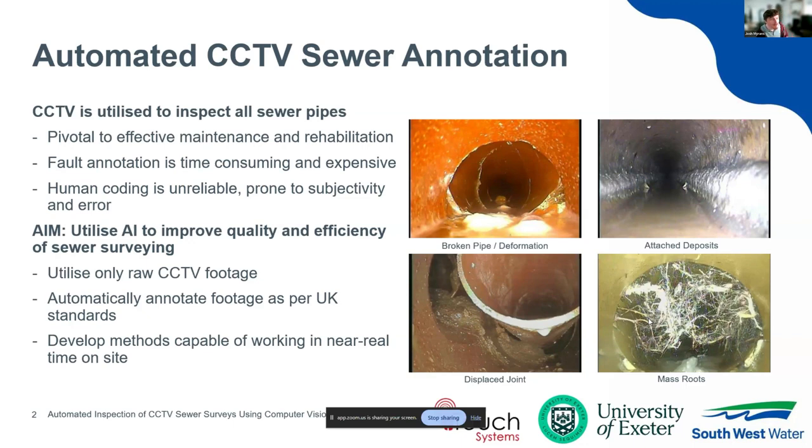That is quite a complex set of codes, and due to the kind of skills required for this, the annotation process and working out what's going on in those pipes can be a really time-consuming and expensive process. In some organizations, you will record all the footage in that pipe and then take it offline afterwards, and a technician in the office will rewatch that footage and label up what's going on. But what's more common practice nowadays is for the camera to be pushed through the pipes and the surveyor to annotate on site, which is slightly more efficient.